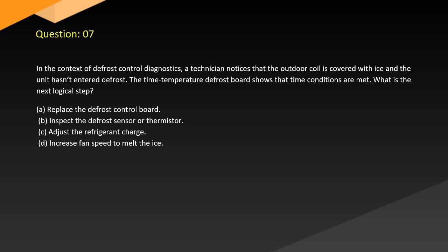Question 7. In the context of defrost control diagnostics, a technician notices that the outdoor coil is covered with ice and the unit hasn't entered defrost. The time temperature defrost board shows that time conditions are met. What is the next logical step? A. Replace the defrost control board. B. Inspect the defrost sensor or thermistor. C. Adjust the refrigerant charge. D. Increase fan speed to melt the ice.